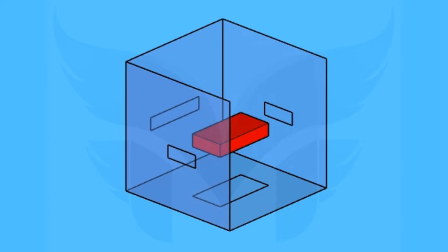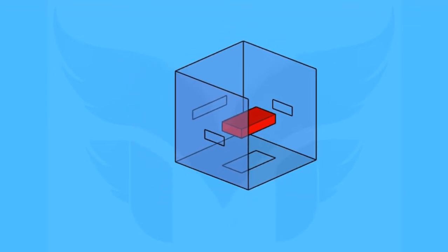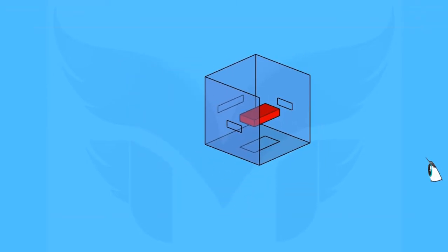Here, we have an object, which is a rectangular slab, placed in the first quadrant in space. The object is surrounded by a vertical plane, a horizontal plane and two profile planes. In order to bring all planes onto a single plane, like a flat sheet of paper, we rotate HP in the clockwise direction by 90 degrees, like this.